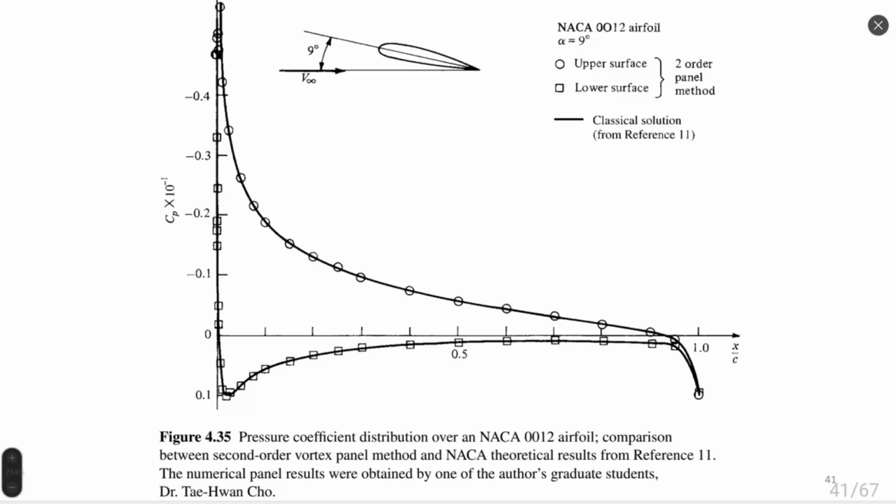And the disadvantage of this method is just because it's simple, it does not account for all processes. For example, we cannot calculate viscous flow. We cannot obtain drag associated with viscosity, because you know that inside the drag force, the biggest part is viscosity and the smallest part is pressure.